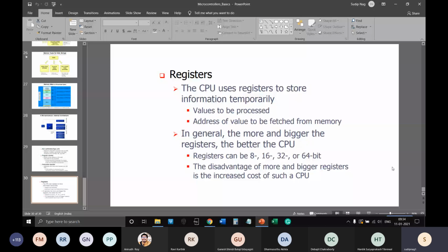So this is one way of looking at my statement. There are other ways also. As I said, sub-threshold logic is another, more modern way, where you never reach the threshold voltage. The MOSFET is always in a triode kind of operation, and based on the exact voltage that you get for a particular input condition, the output will again be some sort of analog voltage. Then by using comparators or some other digital logic schematic triggers, you can scale it to logic 1 or logic 0. That means again some other voltages which are more strictly defined.